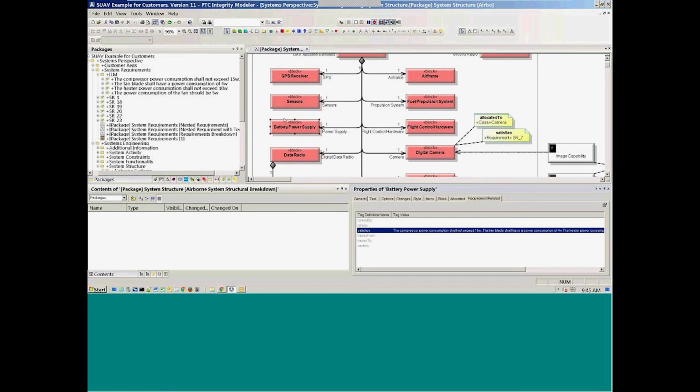So we have a high-level set of traceability within Lifecycle Manager, but a much finer-grained set of traceability within Modeler. So within Modeler, we'll have very fine traces, or a lot of traces going from the model elements. Here we're looking at a very high level at just the system blocks. We'll have much richer traceability going between the different elements of the model. But for the sake of a high-level traceability, we've reflected one aspect of the model, i.e. the block diagrams, the block structure within Lifecycle Manager. So we can see impact changes at high-level requirements on high-level aspects of the model.